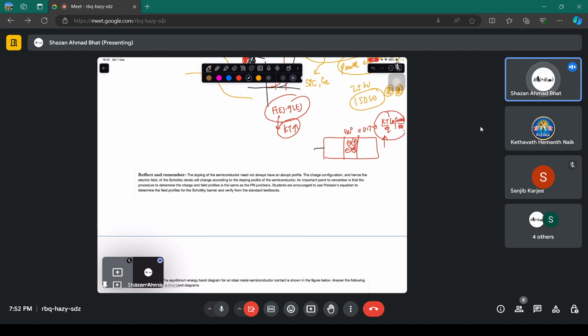How do you measure some voltage externally? You apply a voltmeter here, let's say a multimeter, and measure the voltage. It's not going to measure the built-in potential of this. You see that there is a problem. You are connecting it to the external parts of the diode. Whenever you connect these particular things, a different bending comes in, because these are metal leads. That's why you never measure the built-in voltage of a diode when you connect it to a voltmeter.